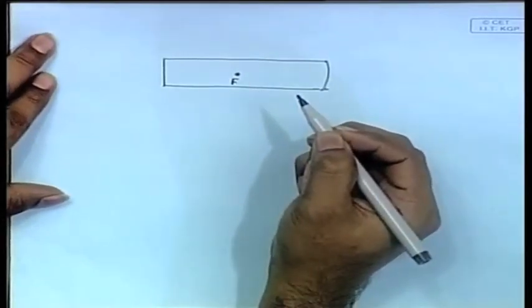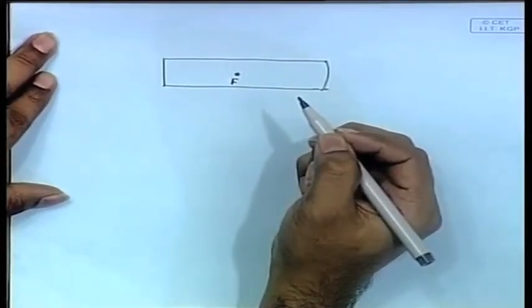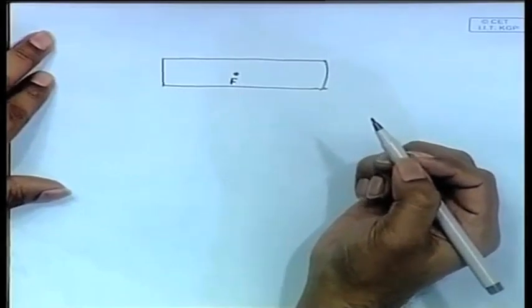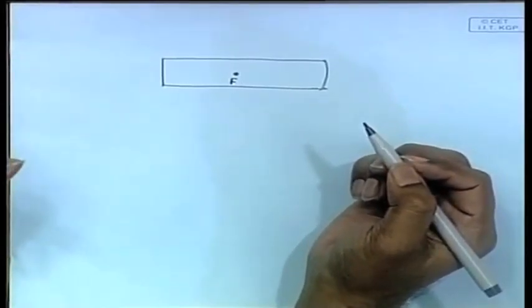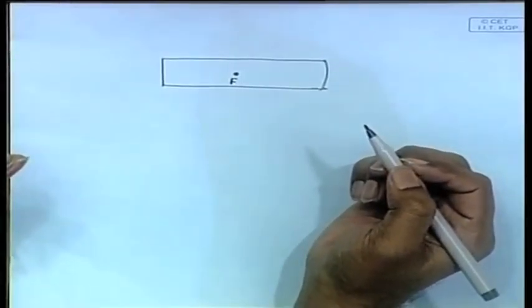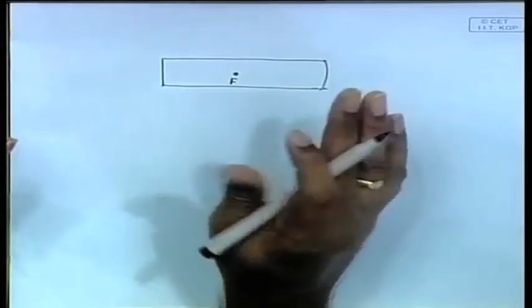Depending on this center of flotation, we always say that the ship trims or moves. Everything we have done about trimming, whether it is trimming aft or forward or parallel sinkage, is about the center of flotation, not about any other center, not even the LCG of the ship. It is about the center of flotation of the ship.